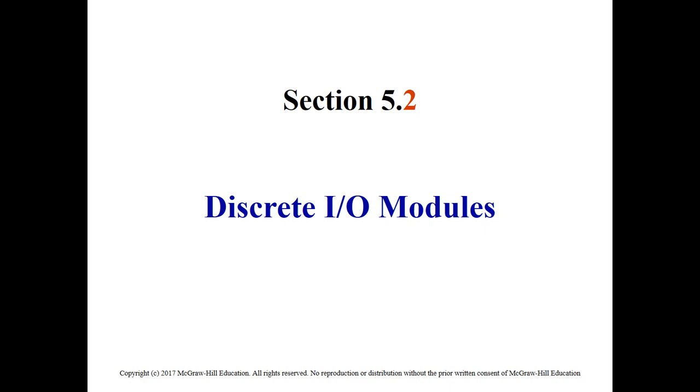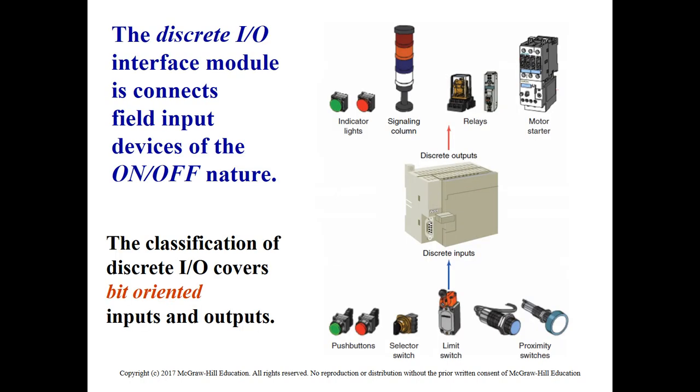to these interfaces. So, for example, as you can see here in the figure or in this component shown in the slides, this is the type of the discrete input modules or discrete output modules, and it can show you what are the types of the device that can be connected with the input modules and what type of the output devices can be connected with the output modules. So you can see here the component that can be connected to the discrete should be a discrete component. That means it has only two options or two statuses, either on or off, 0 or 1.